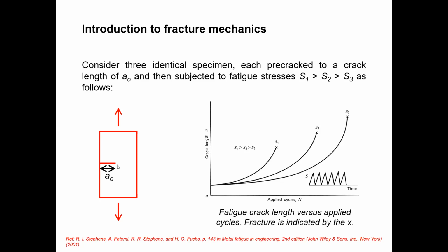So the crack will open like this and penetrate to the other side. With the number of cycles, the effective cross-sectional area, which at the initial point is this, will reduce with time. So with the lower stress, it can survive even though the cross-sectional area is low. That is the meaning here.